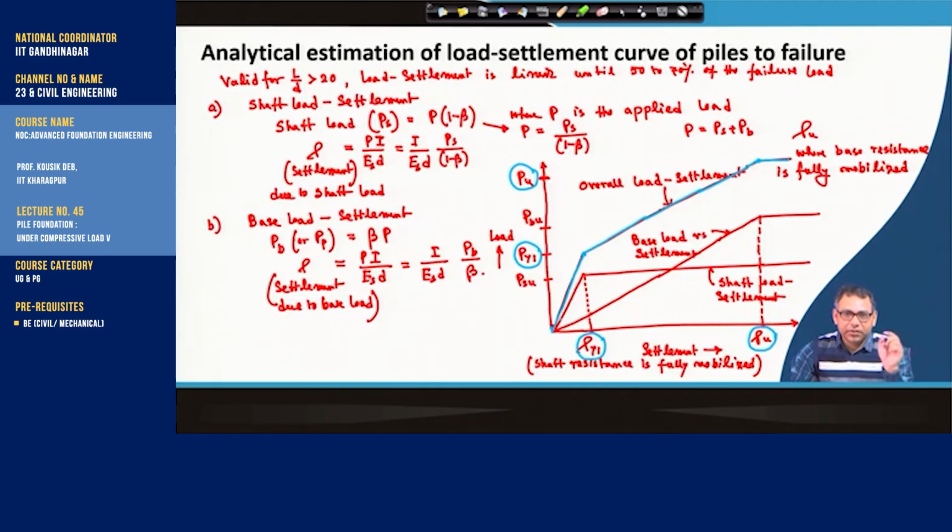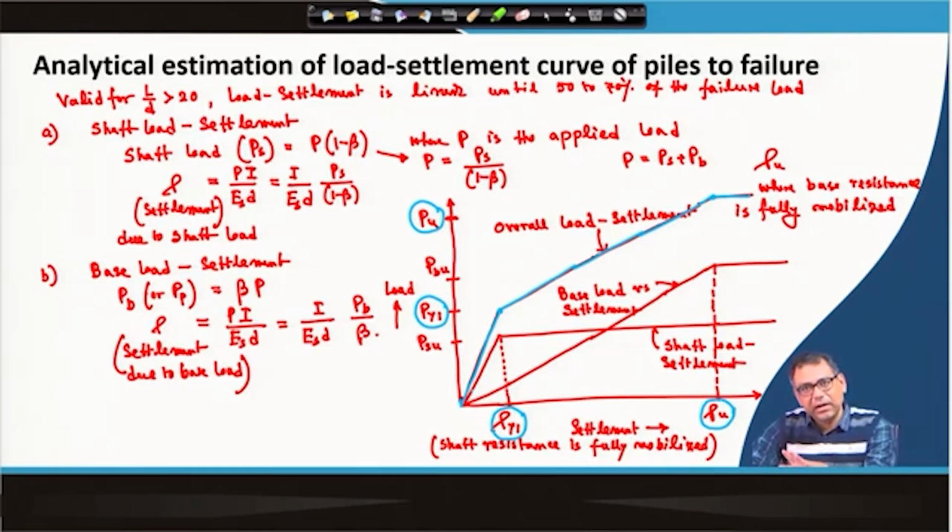So, remember that once the settlement of the soil is completed, the settlement of the pile material will start. That means the settlement of the soil will be completed at the end of the full mobilization of the base load.